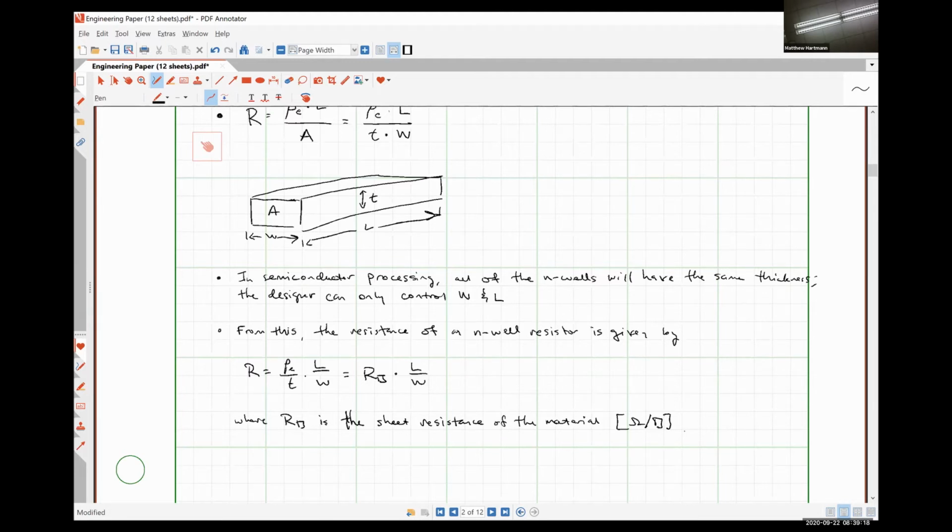Now the units, ohms per square, might seem a little confusing because you may be asking yourself, well, square centimeter, square micrometer, square nanometer? No, it literally means each square, regardless of the dimensions of the square, meaning it could be a 1 meter by 1 meter section or a 1 nanometer by 1 nanometer section, and it is going to have the exact same resistance. That may seem counterintuitive, but that's actually how it works.